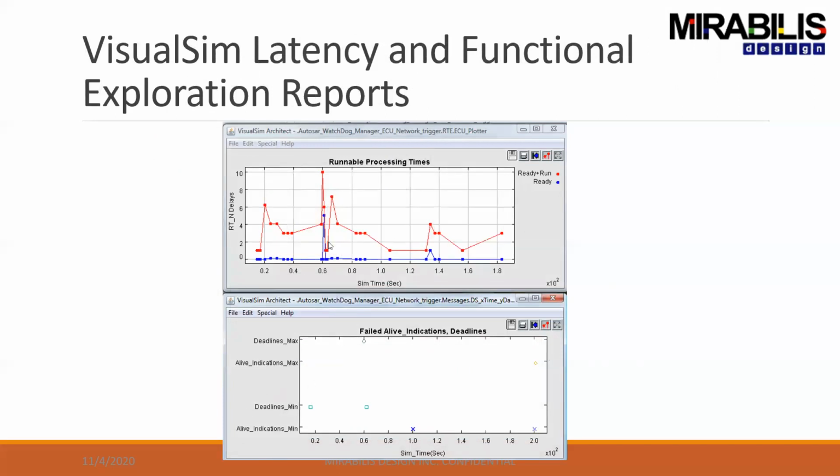And of course, once you do that, you want to see, when you're ready versus ready to run and you actually start executing, what were the delays between each one of the runnables. And of course, you can see at what points the delay maximum or the delay minimum will be reached. So delay minimum is where it goes less than the minimum time that this has to finish. So it's actually finishing faster than you anticipated, which causes problems downstream for other software tasks.